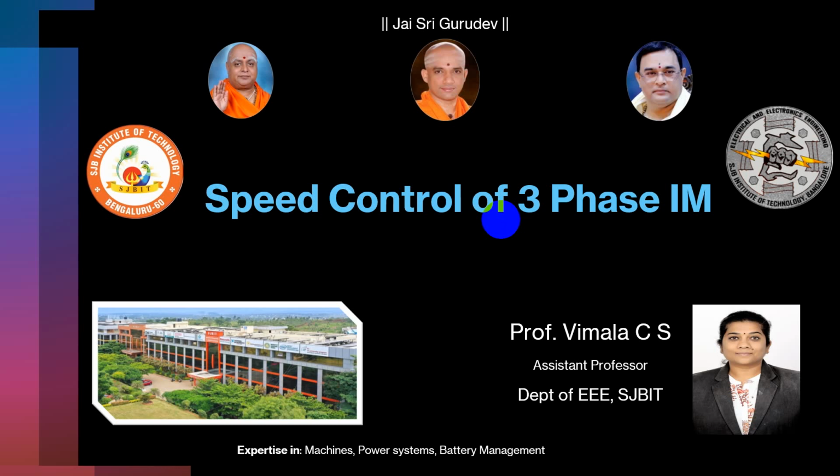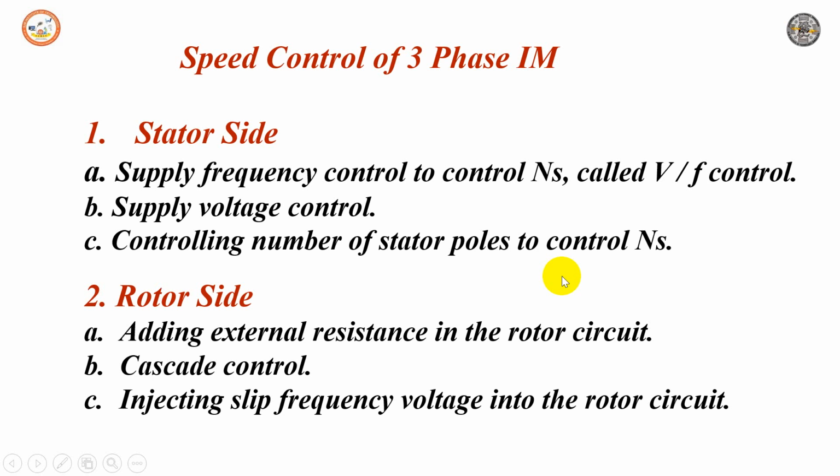As we know, a three-phase induction motor is practically a constant speed motor, like a DC shunt motor. But the speed of a DC shunt motor can be varied smoothly by using simple rheostats. This maintains the speed regulation efficiency in a DC motor. But in a three-phase induction motor, it is very difficult to achieve smooth speed control. If the speed control is achieved by some means, the performance of the induction motor in terms of power factor and efficiency will get adversely affected.